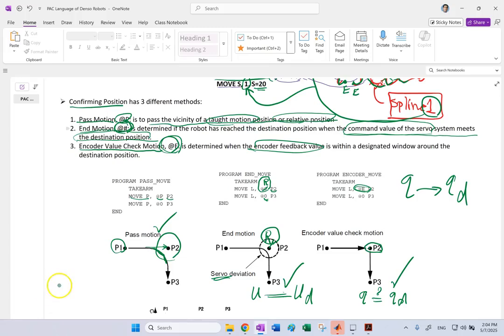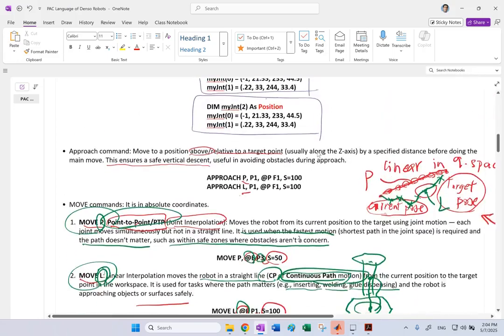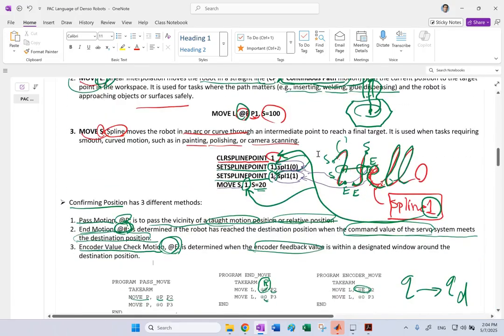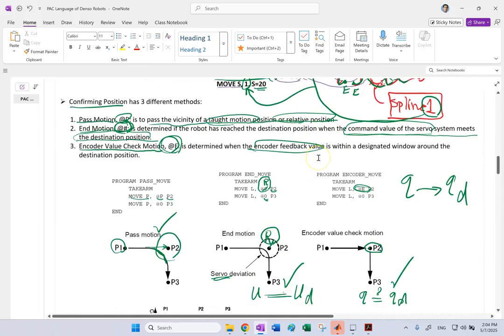It's like a closed loop kind of feedback. It's not real closed loop because you are really looking at Q. You are not looking in the workspace. If you want to do the feedback with workspace, you have to have a way to exactly determine the position of the end effector and orientation of it, which is not a trivial task.